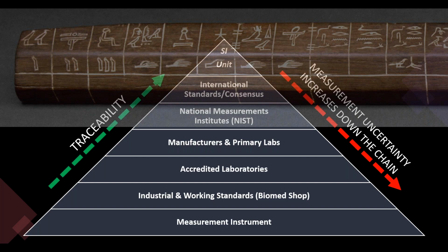So your PRT probes usually have a response time of a minute to 5 minutes. So you're going to get an average temperature. You're not going to see sharp spikes. But the great thing is that they have a much tighter accuracy, usually a 1/10, if not 1/100th of a thermocouple.